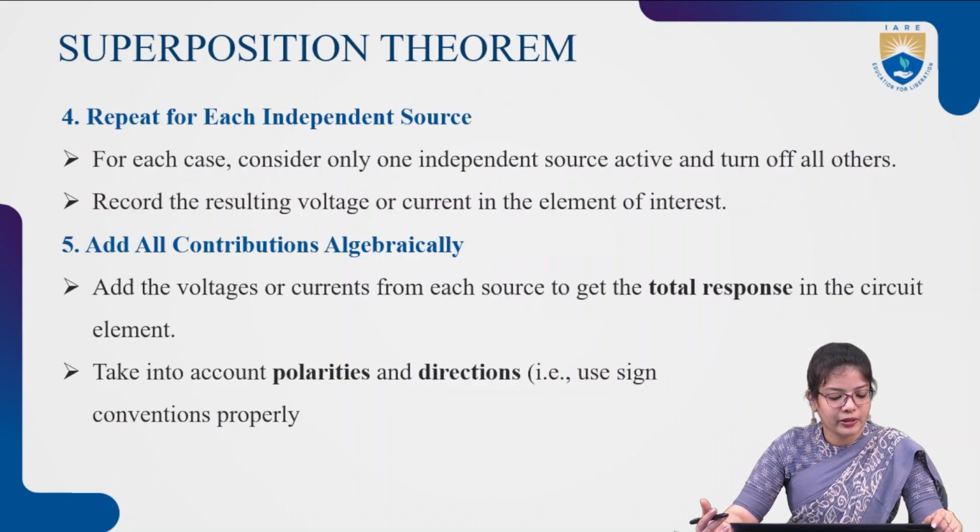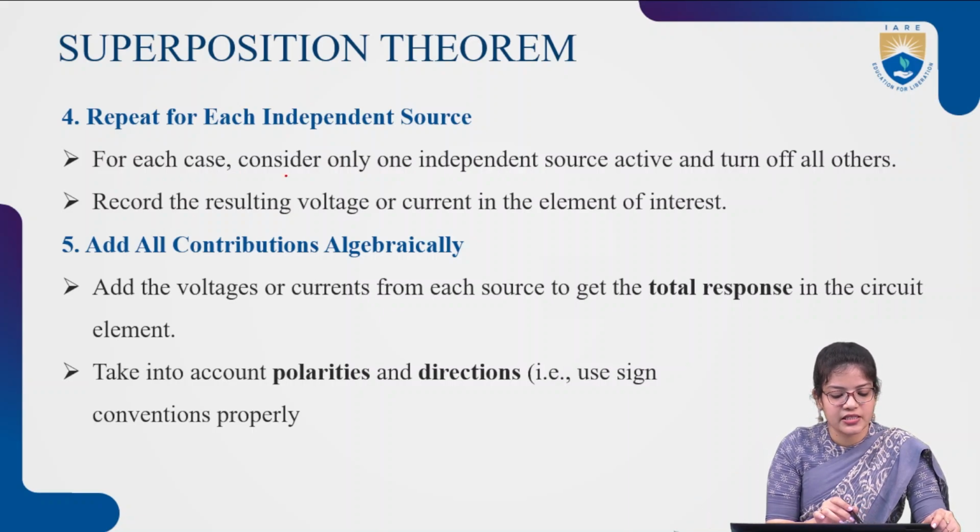The fourth point: repeat for each independent source. For each case, consider only one independent source active and turn off all the other sources.